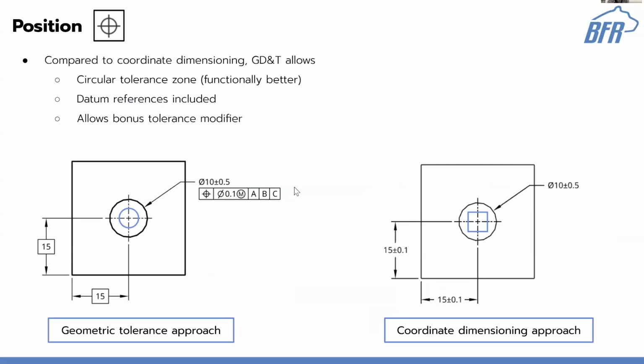But yeah, so here's an example of what the diameter tolerances do versus normal. If you use a circular tolerance zone, this is what you'll see, right? And just some notation stuff. If you see a box dimension, that's called a basic dimension, and that means it's just for reference. This is just telling you where the hole is for the GD&T stuff.